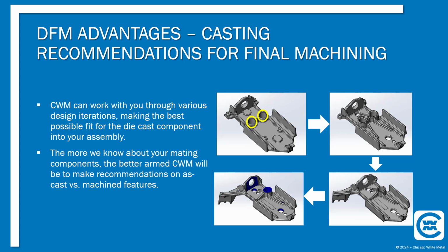So we ended up adding this little tab at the corner here that took the place of another part. So we combined parts, helped in their assembly process. We also got rid of one of these bosses that's in here that's no longer there. That needed machining to start with and no longer needed machining. So overall, a more efficient part for the customer for their application, less costly, and very, very successful.